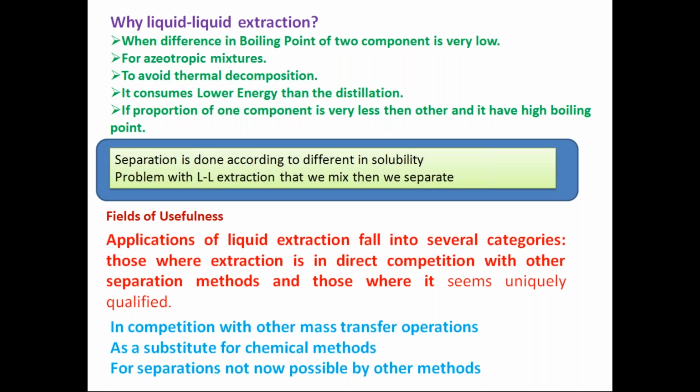Then also, as I have been telling you from the beginning, it consumes lower energy than distillation. Lower energy means, in some cases, energy only to operate the mixer and settlers. If the settler uses gravity settling, you don't require any energy. If it is centrifugal settling, using a centrifuge, because the density difference is very close, then you require certain energy. Otherwise, the energy requirement is almost zero in the case of liquid extraction. And the